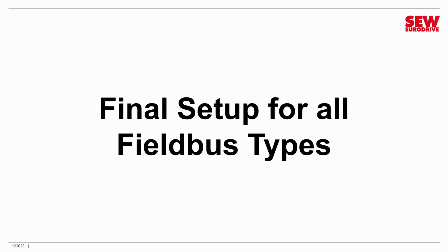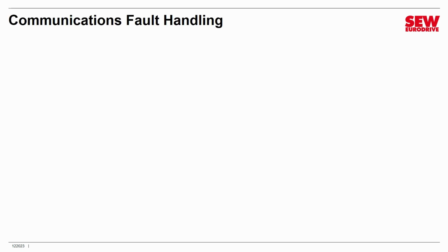This applies to all Fieldbus types, whether you're using classic Fieldbus, using a gateway, or using a Fieldbus card, so everybody should watch this. First thing you need to do is set up how the VFD handles a communications fault. It is always possible, and indeed it's very common, to lose communications in a Fieldbus-based system. Of course, you need to know how to handle this so things will not go haywire on you.